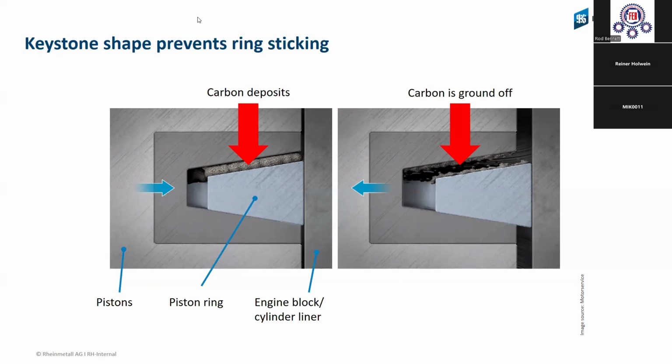But in this situation, in idle speed, as I said, we're not sealing the ring perfectly. And in this situation, they build up carbon. In the first ring groove there was a lot of carbon inside. And this customer asked me, "Oh, Rainer, what can we do?" I said, "Sorry, yeah, maybe you can pull up this engine sometimes in a high load condition, so that the carbon